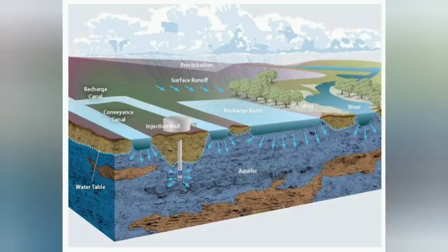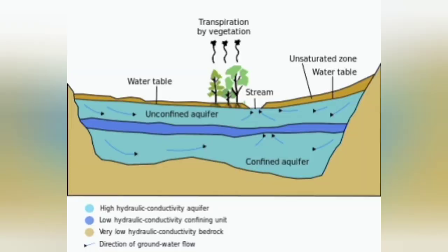There is a maximum rate at which water can enter soil at a particular point under a given set of conditions. This rate is called infiltration capacity. The actual infiltration rate equals the infiltration capacity only when the supply rate, rainfall intensity less rate of retention, equals or exceeds it.